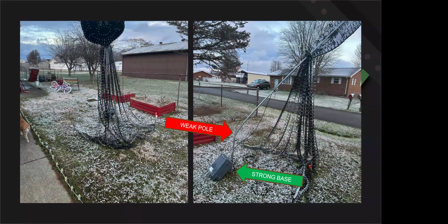I would always put your guy wires up as high as practical. That doesn't mean at the very top. That means get them up as close to the top and make your connections where you can. Definitely no farther down than a third of the way would be my recommendation. But if you can get them up three-quarters of the way, seven eighths of the way, you're much better, much higher up.